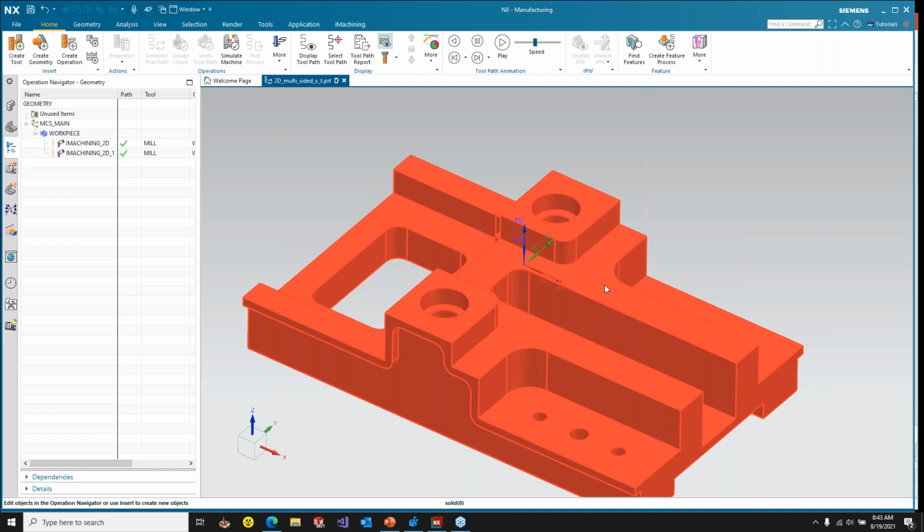In 3D iMachining, is there an option to engage from outside in the open part? In 3D iMachining, and this is just a general thing for 3D iMachining, when we find a level to cut at, a Z level, if it is open, we approach from the outside and we go in. So we only helical entry if there is no other option.